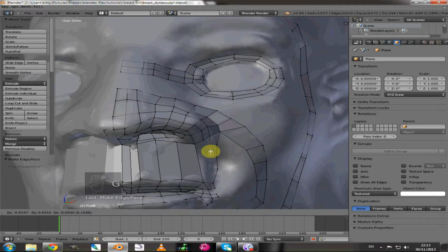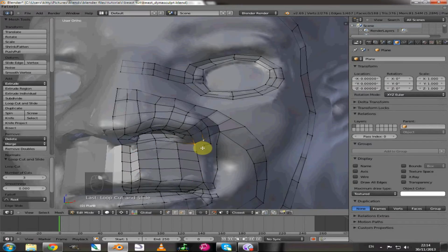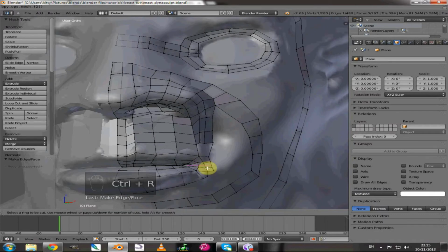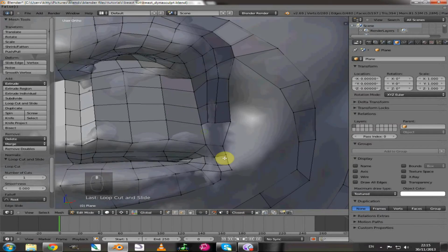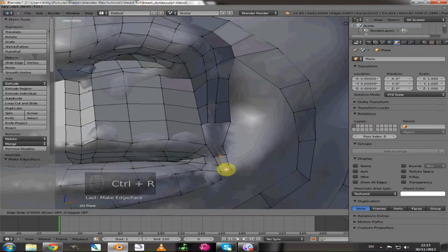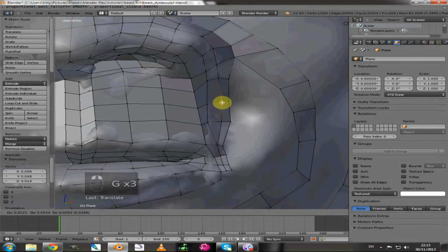And now I'm drawing out again and connecting that crease between the cheek and the mouth to the corner of the mouth. And you'll see immediately that we've got more edges than we need, or than we can successfully join up. So I'm going to create down at the bottom a diamond quad, just like that.